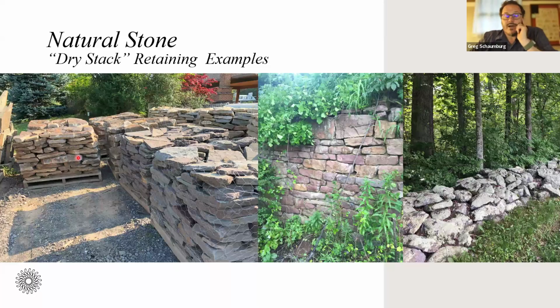But one of the things to keep in mind, and that's why I talked about it when you order, order a little bit more overage, because every time I've ever opened a pallet, I found this. What you'll find is all the good stone material is squared out in the edges, and the fill material and stuff that is seconds or less is usually used to fill the center of the pallet itself. So you'll get a great outside part and you'll look at it and go, oh, that's awesome. I can use every bit of it.